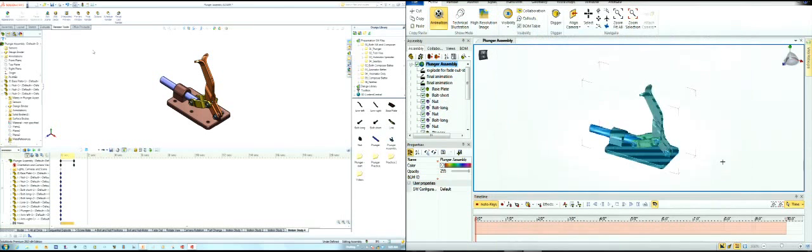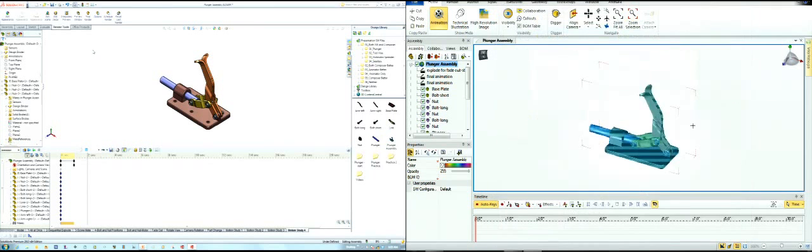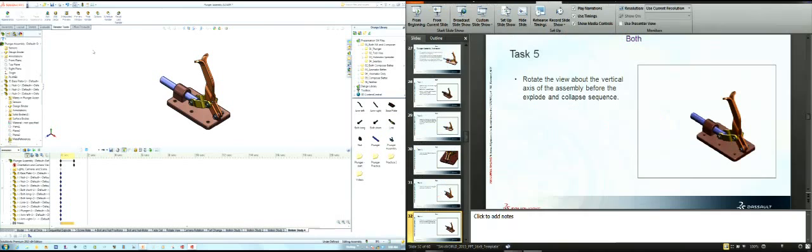Because it's going to take a direct route from one viewpoint to another, I can't go beyond 179.9 degrees, because if you get to 180, there are 2 solutions. So the easiest way is to rotate this 90 degrees at a time. How do I get a 90-degree rotation about the axis of the part?